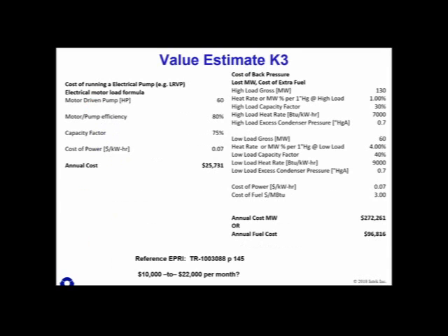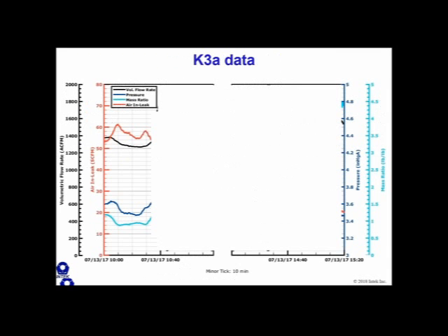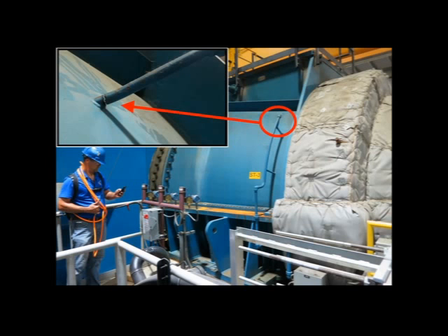One last case study here. We'll go quickly through it. Again, same facility, same setup. I'm not going to ask here. You guys know 1400 CFM is a good flow rate. The air in-leakage was high here. We found a gasket that had a hole in it. We bagged it, and there was another.